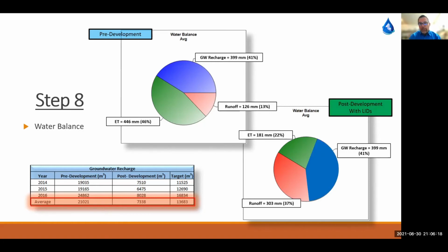In this case, the proponent, through the use of these soakaway pits, which I'm going to illustrate in the next slide, maintains the groundwater recharge at 41%. You see here through this chart that the evapotranspiration is not returned to pre-development conditions, and it's practically, I'm not going to say impossible, because I guess anything is possible, but it's impractical or uneconomical to achieve evapotranspiration similar to pre-development conditions.